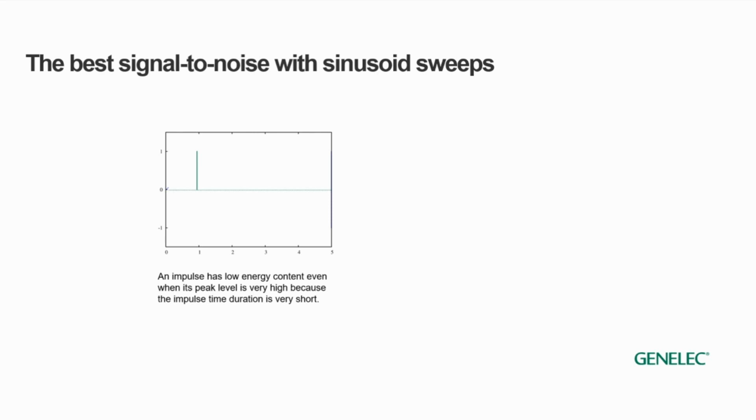With an impulse, this becomes a problem because the impulse is so short, it cannot carry a significant amount of energy unless it has a huge magnitude. If we start increasing the impulse magnitude, we easily overload the capacity of any loudspeaker to deal with that. So this is a fundamental problem that is present if you want to use directly an impulse as the test signal.